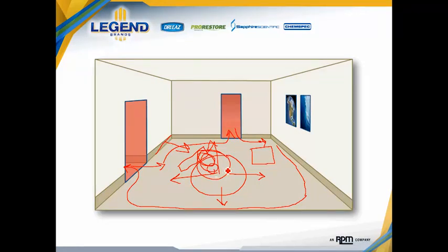So a best way to manage that would be to install one of these axial air movers in the center, as we just discussed, pointed directly down, then bring the contents out towards the center and basically circle those contents around the air mover. When we do that, we generate airflow not only across the surface of the carpet or the floor or the rug, but we also get airflow along the bottom of those contents and ensure that we're drying the fabric and the wood, etc., or the textiles of the furniture or contents that have been relocated within the space.